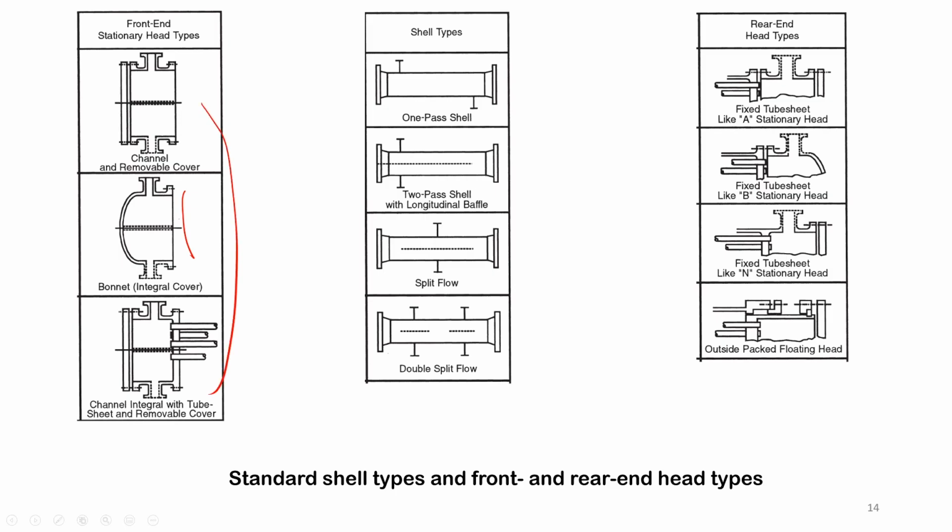In general, if you are using high pressure fluids, curved surfaces are more resistant against high pressure. If you have corners, they tend to create leaks and problems, failure mechanisms. If you have a sharp corner, that is where you tend to have failure in high pressure applications. So you might want to use this kind of geometry to avoid that corner effect.